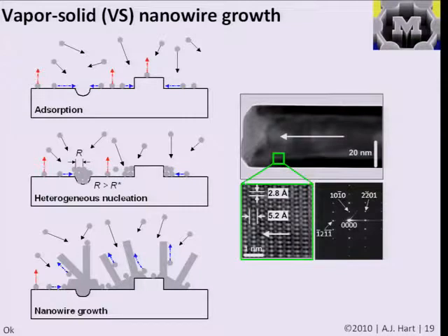So if I, for example, stop the picture here, I would have the picture that I just had on the previous slide, a flat substrate, or a substrate that looks flat from the top, with a whole bunch of clusters of different sizes. Then I would have nanoparticles on a substrate. But for certain materials, if I continue the process and I have a material that has a crystal structure that will grow more favorably in one direction than the other, and I control the pressure and the temperature of the process to enable the growth to happen slowly, I might indeed form nanowires of that material from the substrate upward.